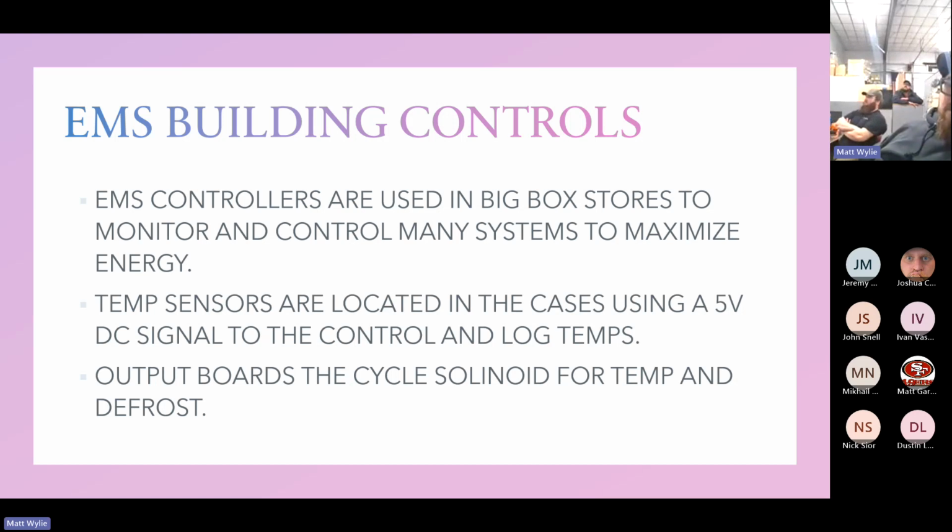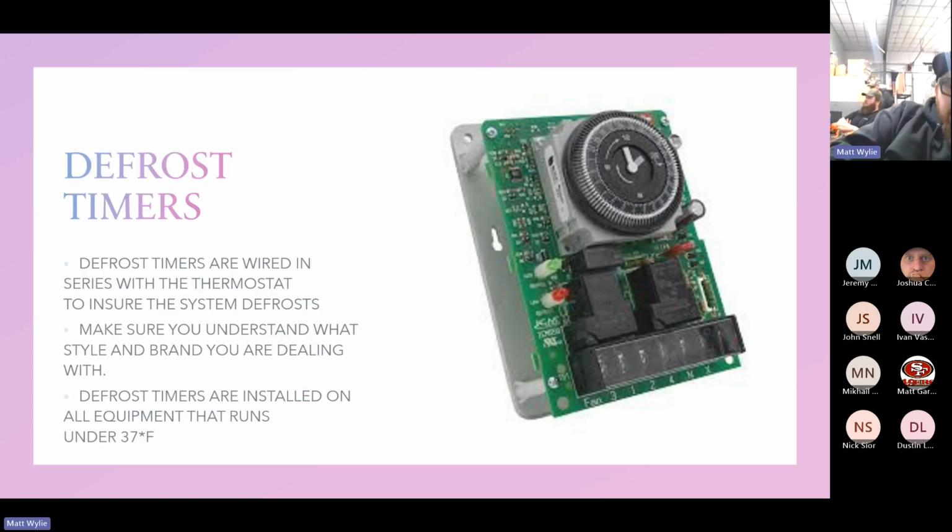Output boards on the case are what cycle the solenoid for temp and defrosts. Then we have our defrost timers, which are wired in series with the thermostat to ensure the system defrosts.